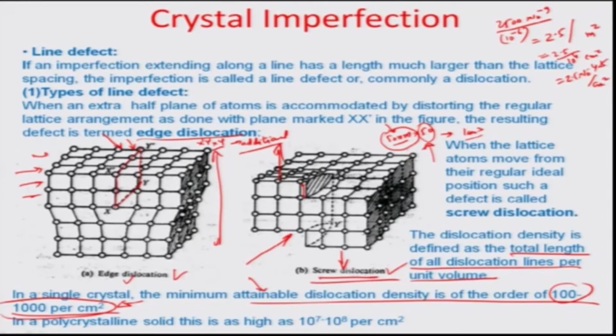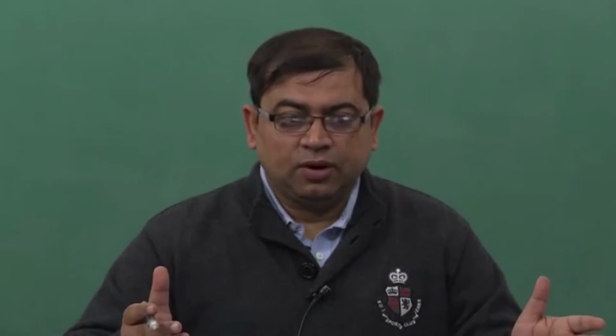So, it so happens, as I am going to show in the next few slides, that the actual modulus of elasticity or the actual shear modulus, if you model it from a lattice viewpoint, and then try to see what happens because of dislocations, you will see that the moduluses are quite far apart, probably 2 or 3 orders of magnitude apart.